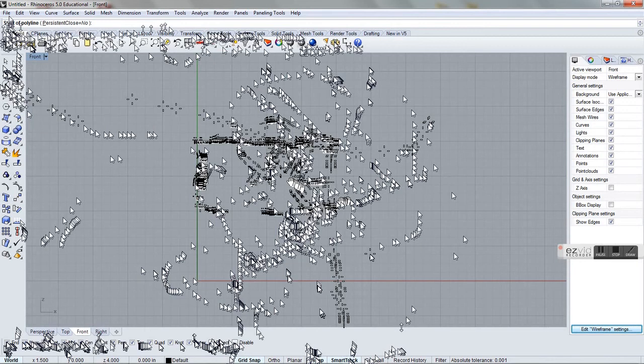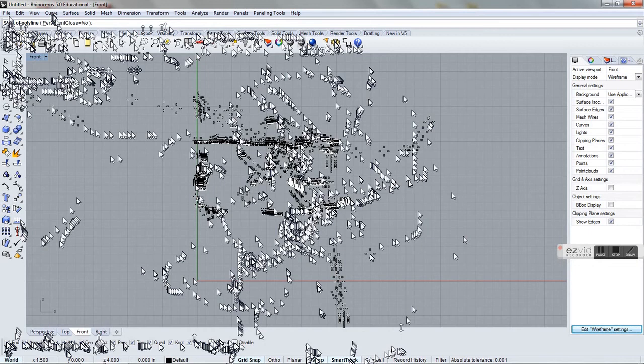So I can left click on this line tool. There's also a small triangle I can click on, and there's a bunch of different ways of constructing lines. If I want to keep that box out, I can click it and drag it out like that, and it will stay on my screen. I don't need that right now. The other way you can access commands is through these pull down menus. I can go to line or polyline, click polyline, and again that will start the command.